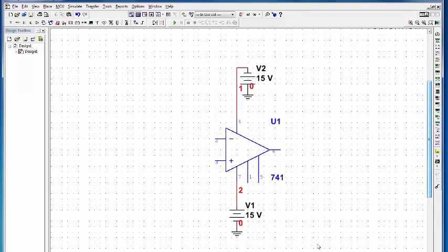And now I'm looking at the textbook problem. It says I want the plus to go to ground also. I'm just going to do a Control C, copy and paste. Put my ground to pin 3. And the rest is putting components that we already know about. So I'm going to pause this a moment. You don't have to watch me place all the components. And then I'll come back after I've placed all the resistors around here and we'll look at how to run the circuit.